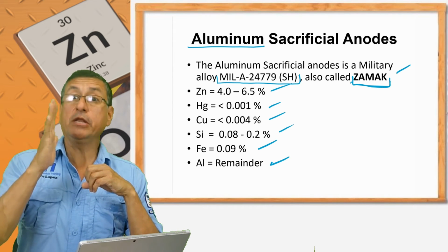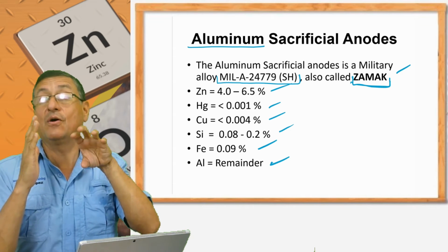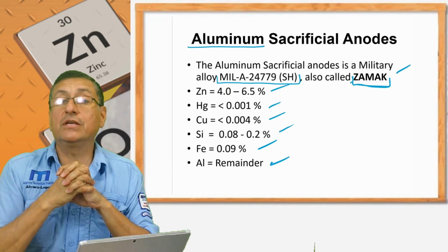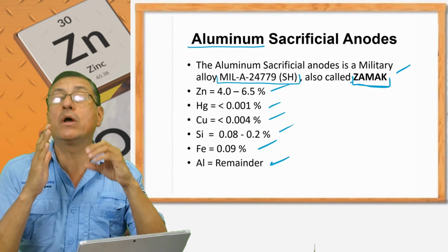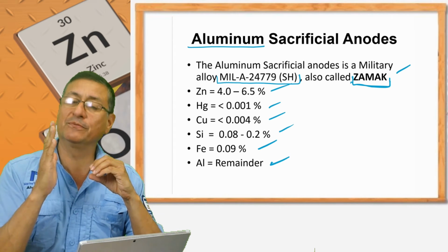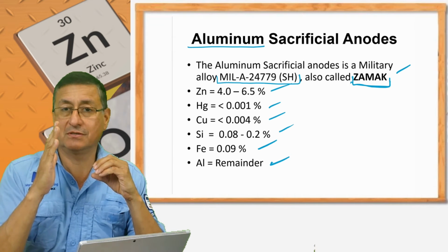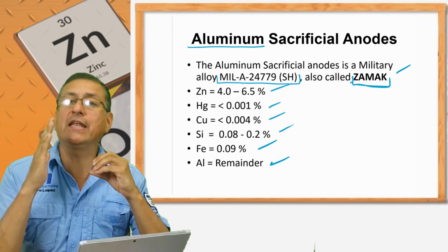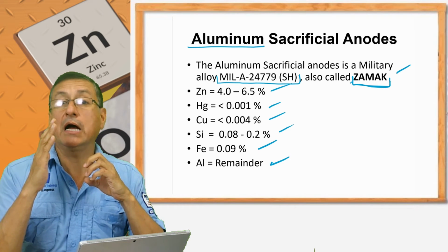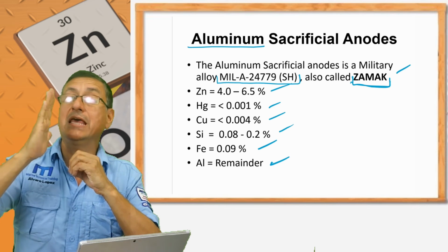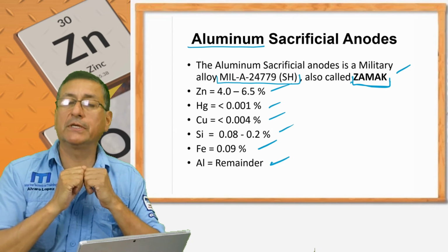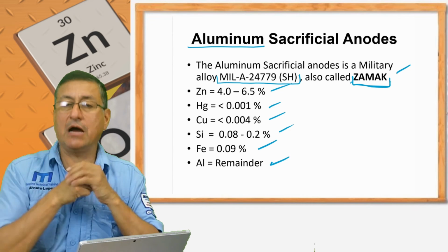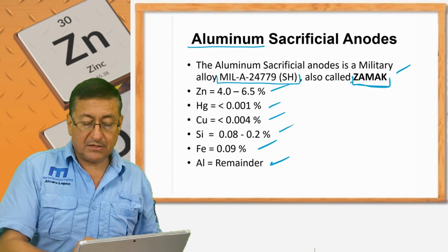Can I protect aluminum with a sacrificial anode of an aluminum alloy? Yes, because the marine alloys for sacrificial anodes have a lower level of energy in comparison with aluminum. For that reason, there are anodes in aluminum alloys used for aluminum boats, because the level of energy of this alloy is low, and of course this alloy works properly to protect the aluminum hull. Yes, there are sacrificial anodes in aluminum alloys good for aluminum boats. Now we are going to check that situation.